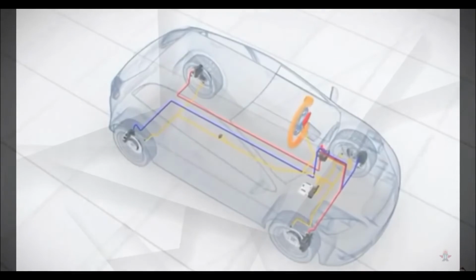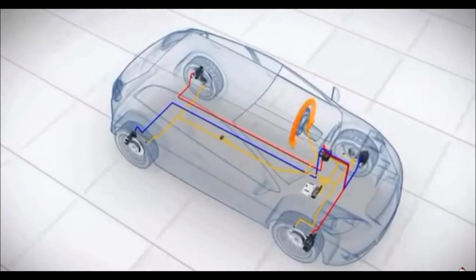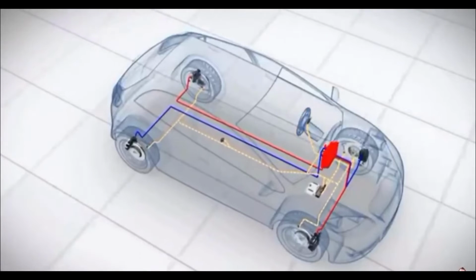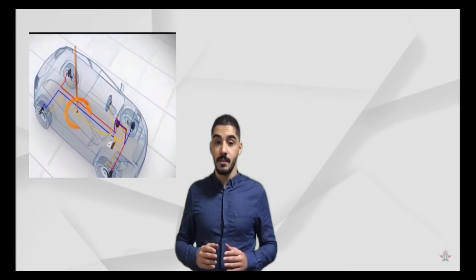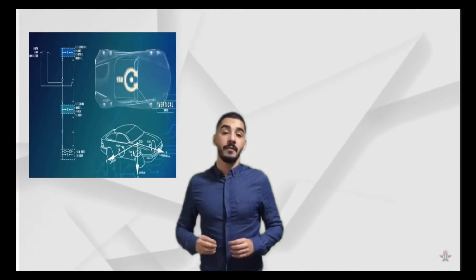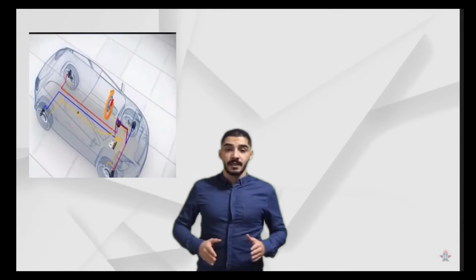This system consists of many sensors, the most important of which are: first, a steering wheel angle sensor that determines where the driver wants to steer. The second sensor is located in the middle of the vehicle from below, which is the yaw rate sensor, and it is responsible for determining the angle of rotation of the vehicle's body during a sudden change and adjustment in the vehicle's trajectory.